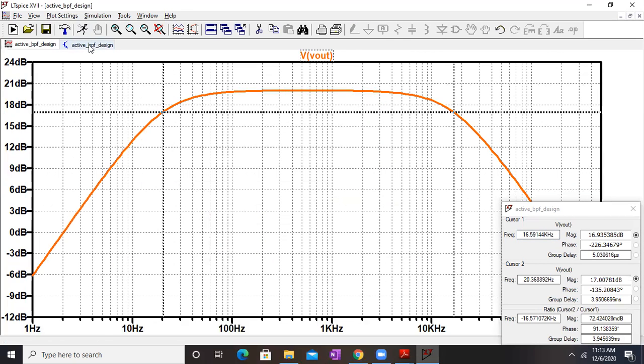That is due to the first order nature of the filter. So over here, I think if I tweak it properly, let me check it out. Oh, no, around 17 dB. It's around 16 point something. So we are not getting 20 kilohertz. We are getting 16.23 kilohertz.